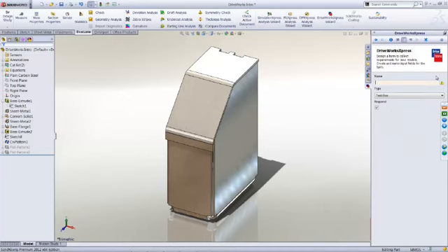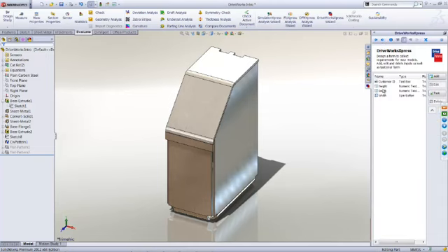Now as for the width, maybe I decided that I would like to use a spin button. Alright, so let's give a width here, and for my width, my minimum value would be 28, no, not very good, let's give it 30. Okay, and my maximum value would be 125 and the increment will be 5. That means I'm allowing the potential user to define the width in increments of 5. That's all he or she will be allowed to do. Alright, and that's what we will require the user to input.